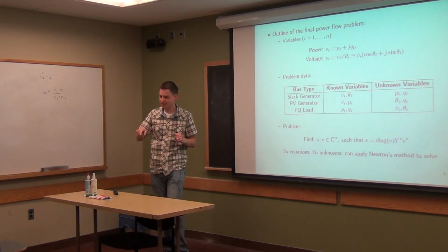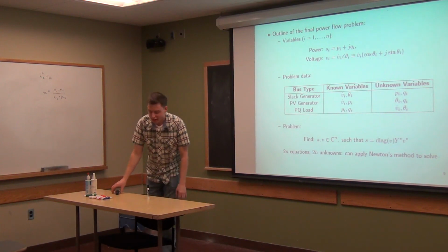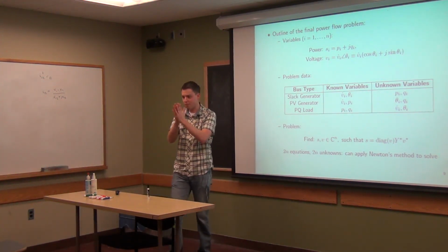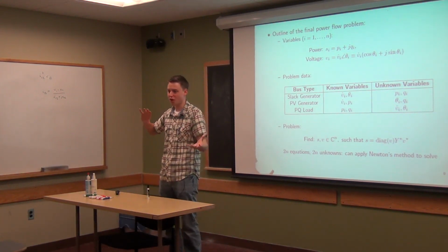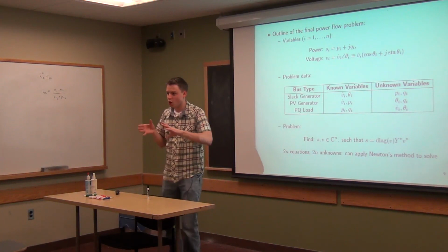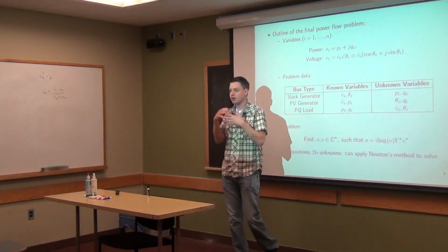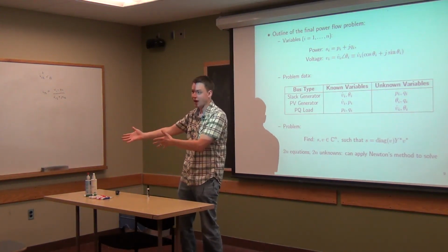We know PQ of the PQ node. Yes. From their impedance? Yeah, in reality, this is the kind of thing you might want to actually measure. You don't really know it. And what's really happening is it's a big dynamical system where generators just react to it. We're assuming for power flow analysis that we do know it, based on, say, our machine learning prediction about what people are going to consume. We can do a similar one for reactive power, certainly.